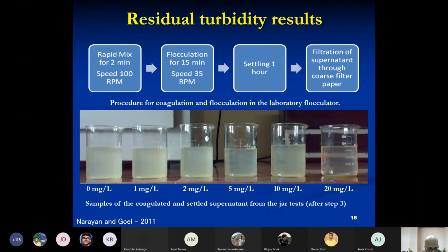You can go to, like I said, we've done it for 24 hours, we've done it for 48 hours. So there's literally no limit to the maximum. But remember that in practice, when you're designing a process, there is obviously a limit in terms of your budget. You can't have an infinite budget. So it all comes down to what you can afford to design in terms of a tank. Most people design for a settling time of 3 hours, and like I said, the minimum is 1 hour.